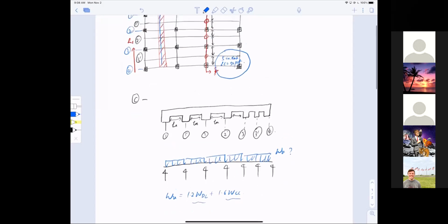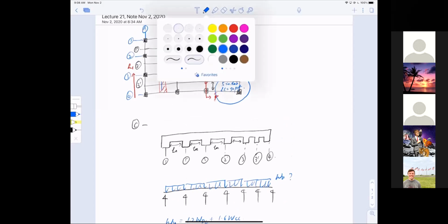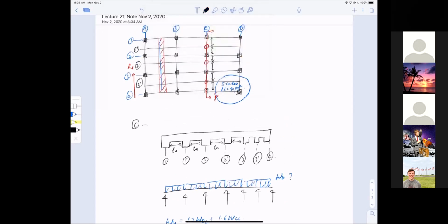How to do that? First, before you do calculation, I want you to visualize where is this strip of slab you're looking at. What is the load that you're looking at? The load sitting on top of it is basically 1 foot of strip. Let me use a blue color here, okay? 1 strip with a width of a foot sitting on top of it.